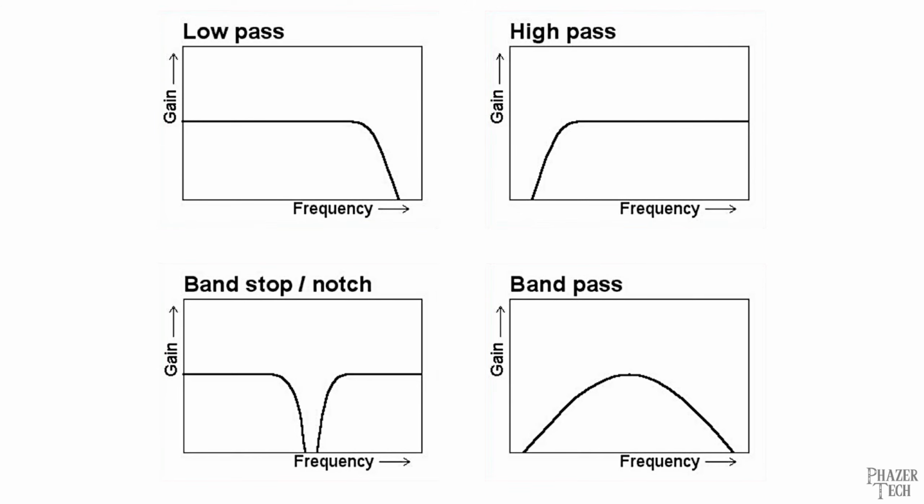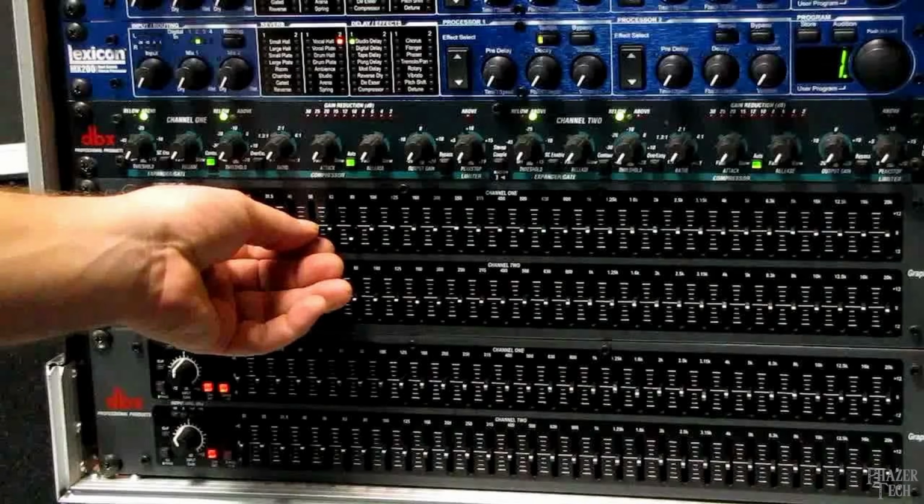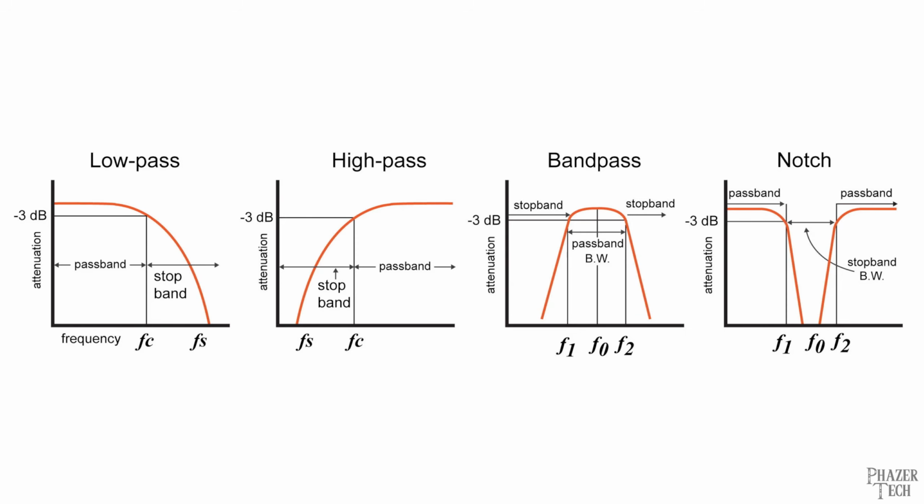You can design them in such a way that they don't completely remove any frequencies, but simply reduce the amplitude of specific frequencies. If you're a musician, then this concept is extremely important for shaping your tone. This is what EQ controls on your amplifier or pedal are for. But the problem with cascading filters like this is that they can only attenuate the signal, which means the signal you're left with is always going to be weaker than the original signal.